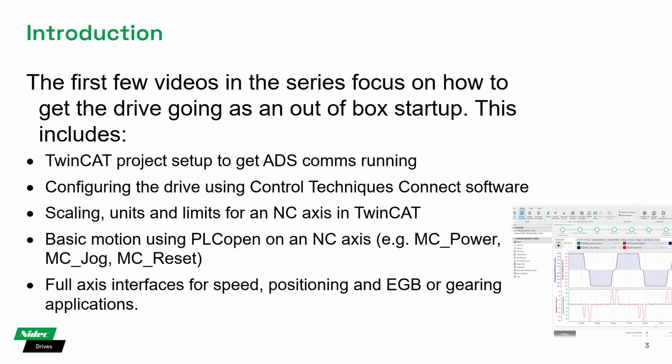The first few videos in the series focus on how to get the drive going as an out-of-box startup, which includes TwinCAT project setup so that you can get ADS comms running. That means you'll be able to get communications between the Control Techniques Connect software and the PLC or IPC that you're using in the TwinCAT environment.